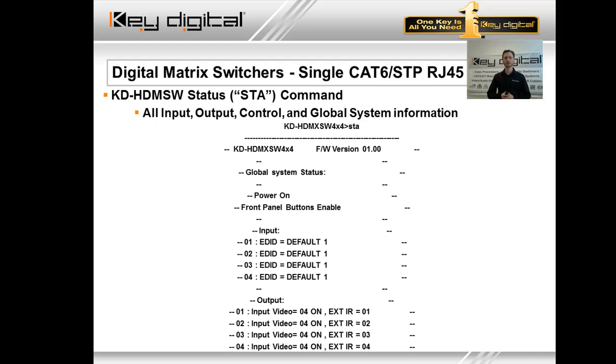Status command. Again, entering status tells you what's going on at the current moment with the switcher. You got your input status command. It tells you the defaults or the EDID setting that's related to that input. Does not tell you, as in the Hercules or Digital IQ, what's the audio format, what's the video resolution, etc.